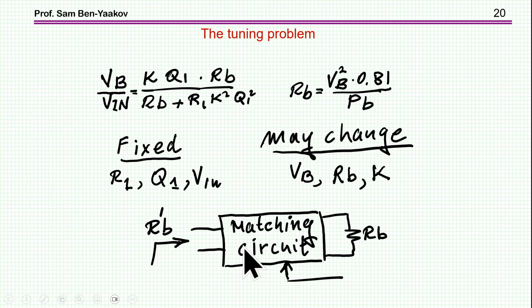In fact, like in a buck converter, the input impedance will be the output impedance divided by D squared, the duty cycle squared. So by having a converter placed after the rectifier, between the rectifier and the battery, we can actually do an impedance matching or a load matching, and then go back to the operating point that we want to work at.